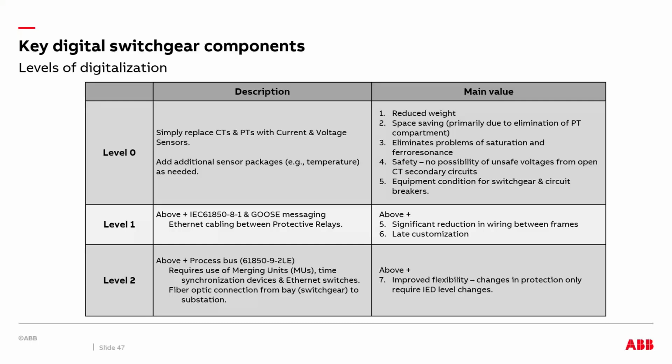And you eliminate the hazard of open CT and also CT saturation, and it's safer for the maintenance personnel and also operation personnel. The equipment condition is also monitored. So this is the base level, depending upon how comfortable the design engineer is with introducing digitalization into their own switchgear.